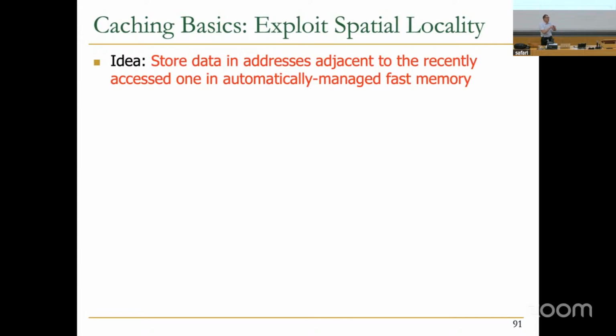That makes sense, hopefully, right? The processor accesses address X, but when it brings data, it doesn't just bring the word that is operating on that address X, but let's say 16 words around it, and brings it to the cache. And the hope is that you're going to access a lot of those words also. That's the idea, basically. Simple.